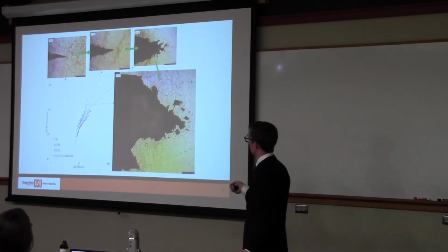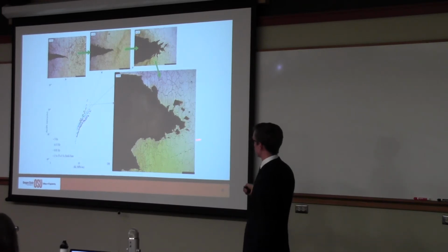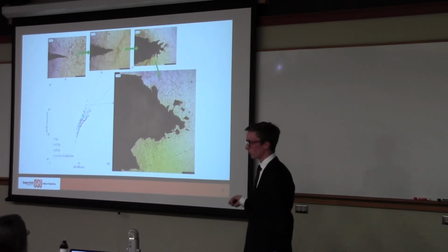And then what happens? This is the highest stress intensity where the crack growth rate has broken away. And so we see in this sample where the transition happened, where it branched off in these sharp little triangular cracks, and then one of those paths got dominated with void growth, and it chooses that one path.